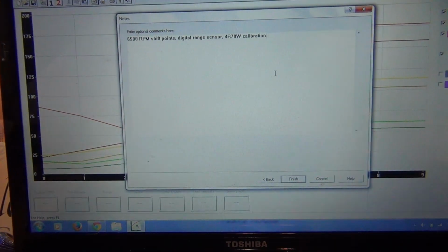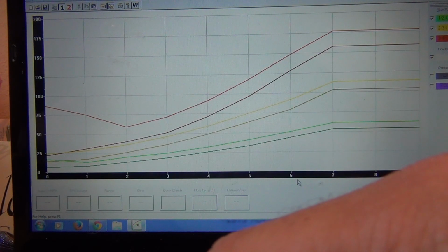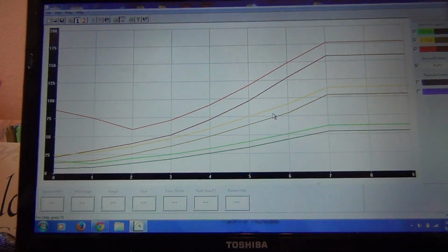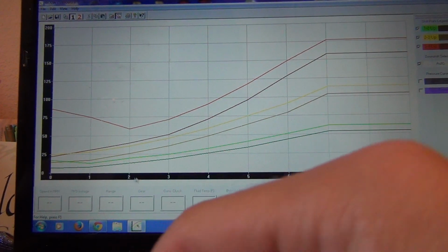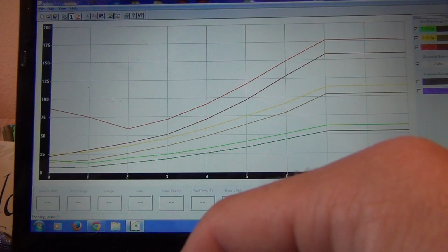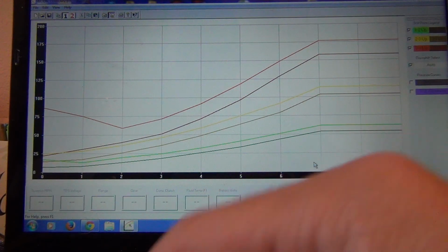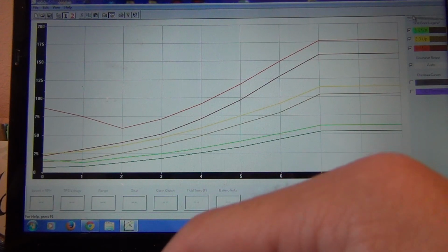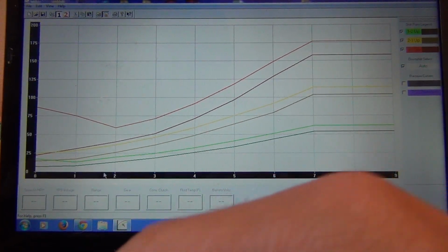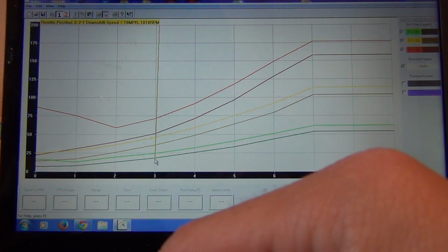If you want to make notes, it'll tell you, so in your own stuff, you can put in there what works and what doesn't. Okay, so it's pretty self-explanatory at this point. Your bottom here says your throttle position sensor is a 1, well, technically 0 through 9. So 0 is you're not touching it, and 1 up to 9 is wide open. In this case, let's start with first and second. Your average 1, 2, and 3 is going to be your cruising.